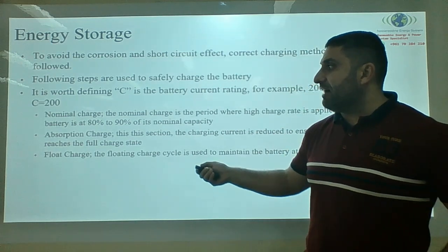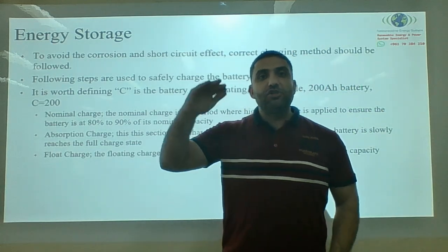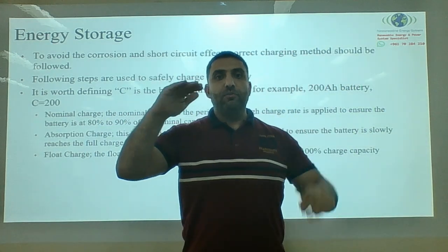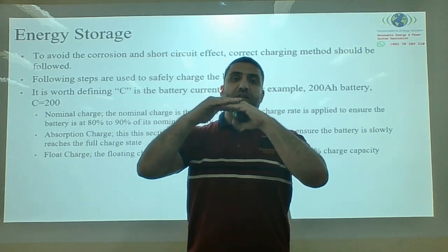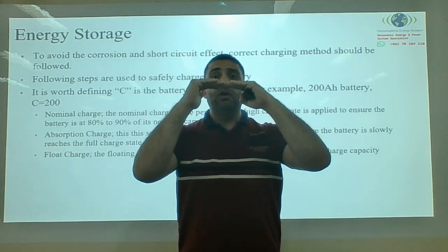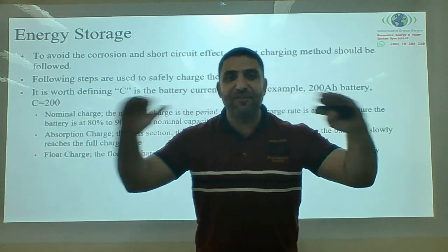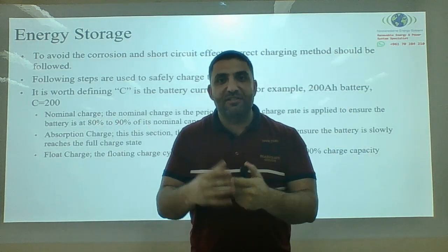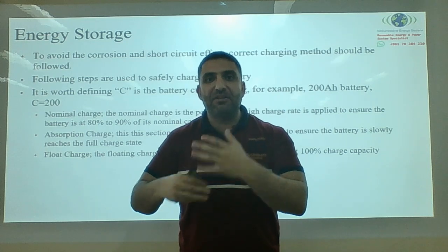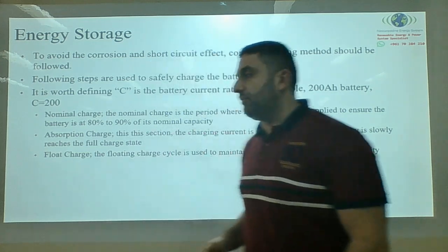And after this, I have the floating charge. The floating charge is chosen to make sure that after the battery is at 100%, it will stay at this value, because there are losses. Nothing is 100%. There are losses, and the battery tends to discharge itself slowly.